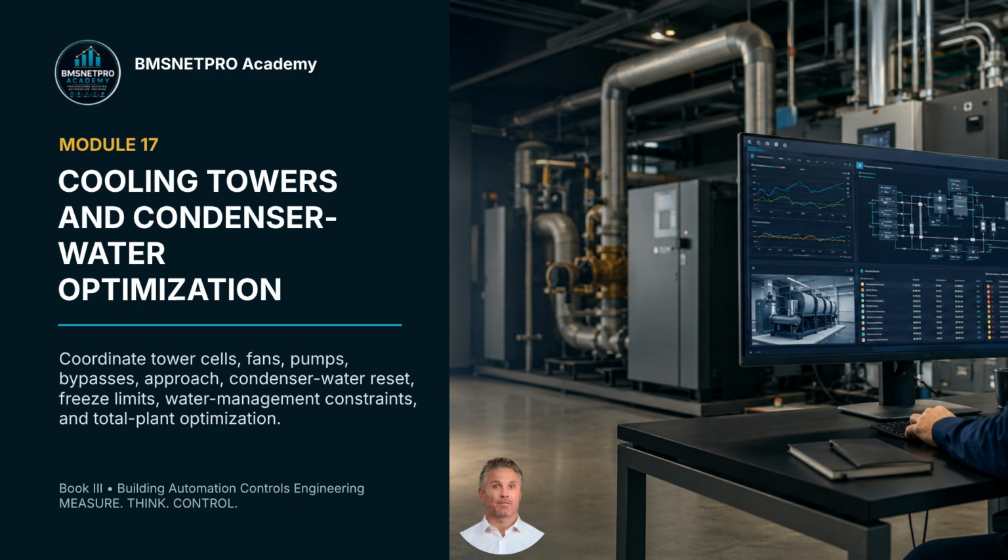Welcome to Module 17, Cooling Towers and Condenser-Water Optimization. In this module, we connect tower control to total plant performance. Lower condenser water temperature can reduce chiller lift, but tower fans and condenser water pumps also consume energy. The professional goal is not the lowest tower leaving water temperature by itself. The goal is the lowest total plant energy while staying inside chiller limits, tower limits, water management requirements, freeze protection, and reliable operation.